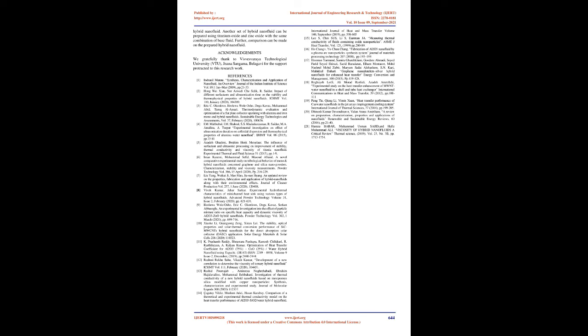Conclusion. A critical review on synthesis, types, and properties of nanofluid was discussed in detail based on previous researchers' findings. Increase in temperature results in enhanced thermal conductivity for all the nanofluids, while viscosity decreases with increase in shear rate. The two-step synthesis process is preferable to the single-step process for preparation of nanofluid, due to control over the volume concentration of nanofluid. Performance of mono-nanofluid is comparatively lower than that of hybrid nanofluid with respect to thermal properties.